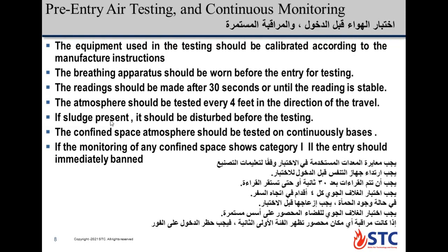The confined space atmosphere should be tested on a continuous basis, maybe every 30 minutes, such as after 30-minute testing, and continue to test the gas or the hazard.